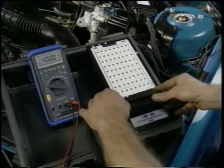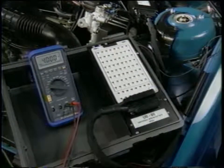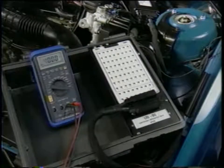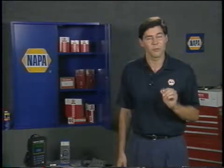Using a breakout box to check circuit voltages and resistance is a lot easier than trying to check each and every circuit at various points throughout the vehicle. Reading voltages and resistance at the breakout box is also a good way to test an entire circuit, not just an individual component. It will show you exactly what the control module is seeing in a particular circuit.